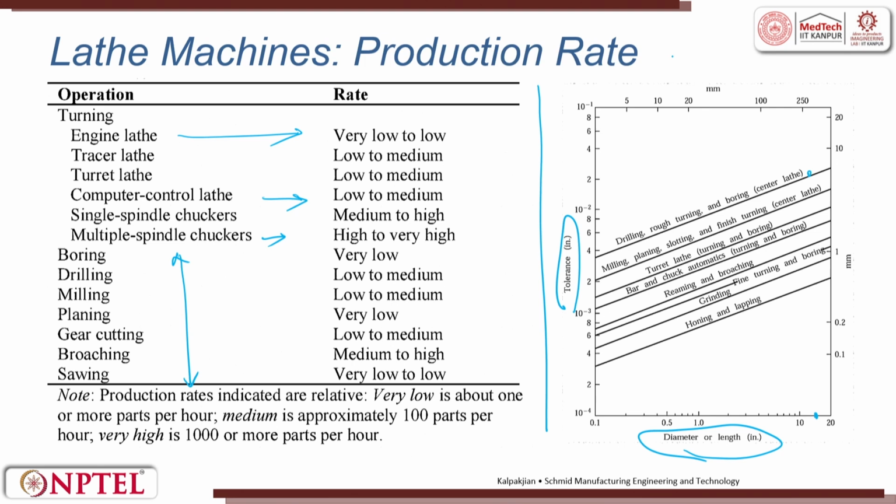That means there is a possibility of defects coming. What is tolerance? Tolerance is when you give a deviation, x plus or minus 10. This x is the diameter of the shaft and this 10 is the deviation it can have. For example, if the diameter is 50 millimeter, you can have plus 10 or minus 10. It is 60 to 40, so a 20 millimeter tolerance is given. So, the part can be at most 60 diameter or 40 diameter. As and when the length and the diameter increase, the tolerance also increases.